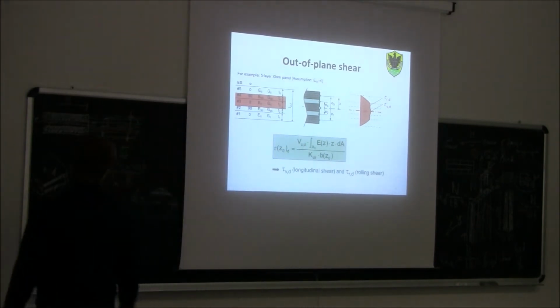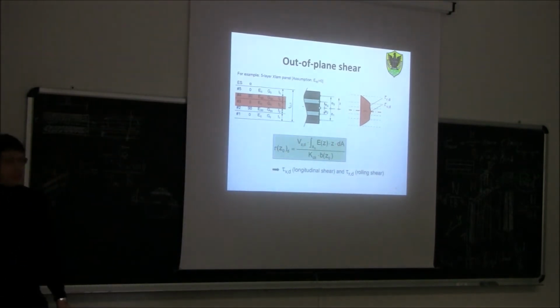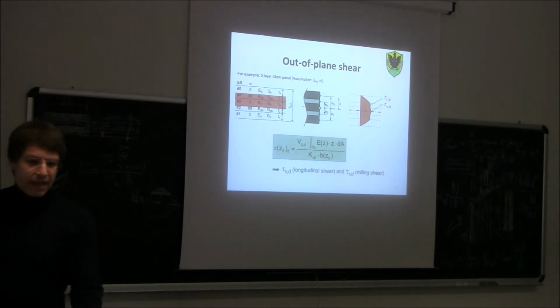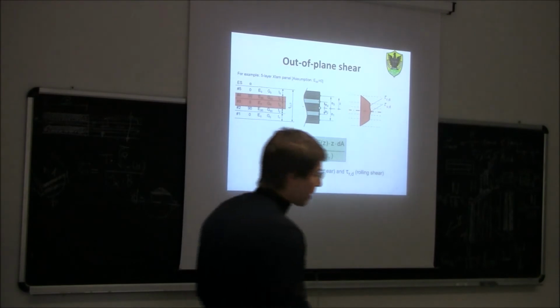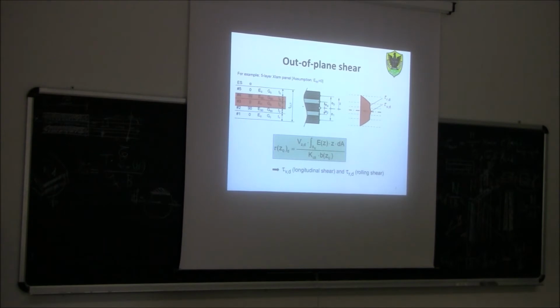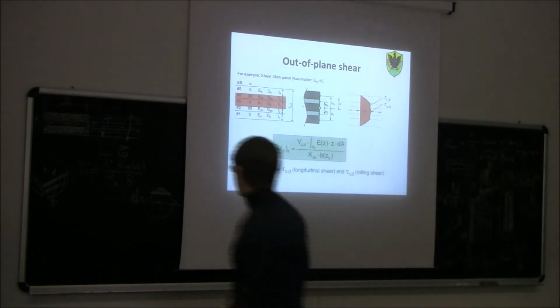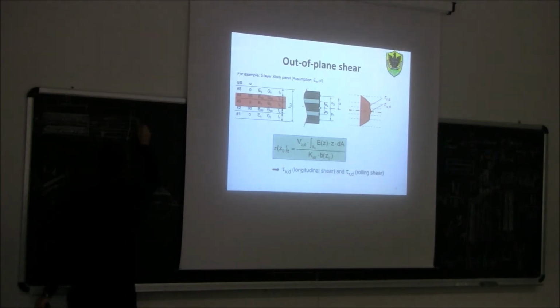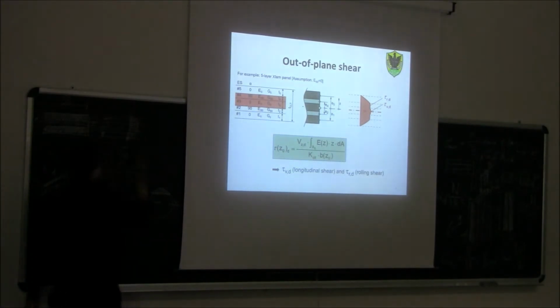Constant. If you remember well, when we studied the second stage of reinforced concrete structures, we were talking about calculating with Jourawski the shear distribution of stresses for a cracked cross-section. In the crack region, the concrete was there but was not resisting, so the trend of the diagram of tau was constant. And so it is here. So this is the diagram of the tau. Okay?